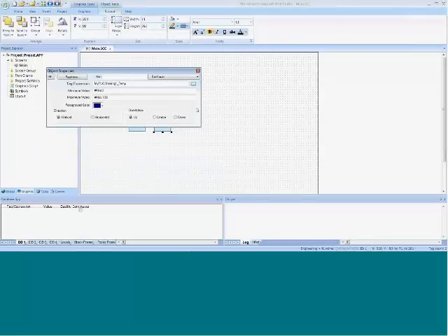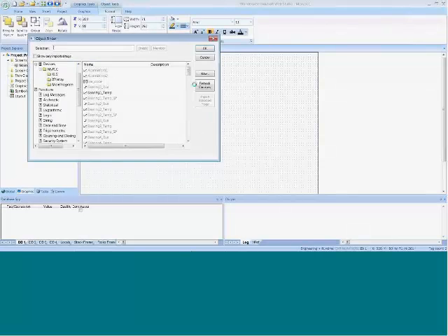When I pick that bearing temperature, notice that it's put it into my tag expression here. If I go back in and look, that one is now highlighted, and now I have 2 tags in my project. It doesn't add all of those tags to my project, just the ones that I've used. And you can refresh and update this based on when the PLC changes take place.